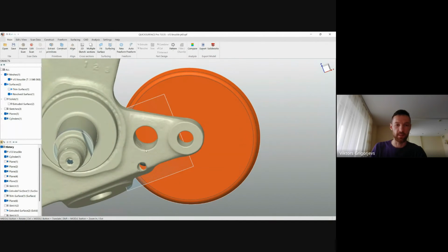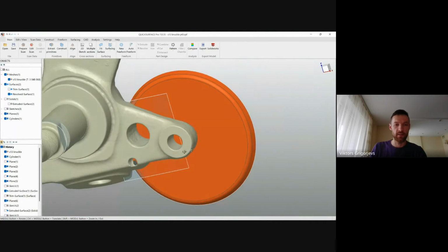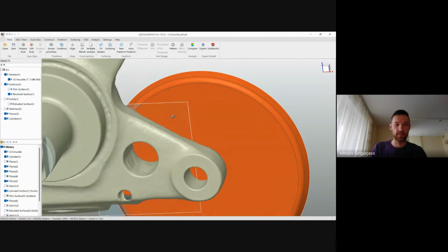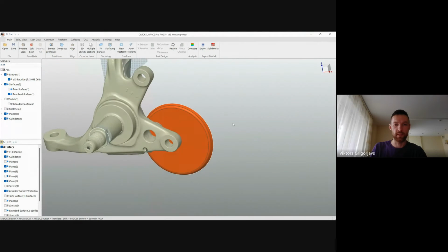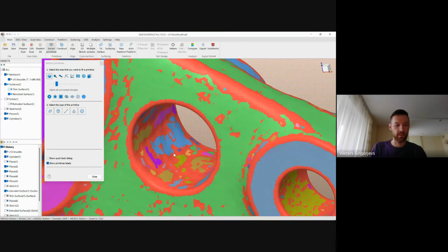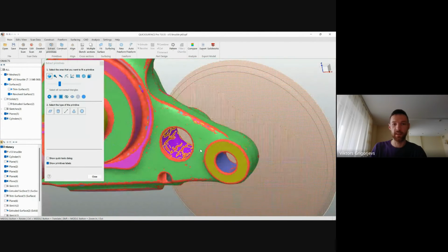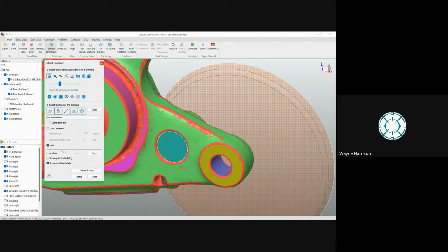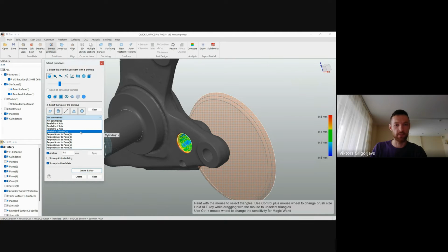Considering we still have this door here, let's create this as one single cutter. I'll just hide this plane, we don't need it anymore. So extract primitives again. The surface is a bit wobbly, not that great quality, but let's put a cylinder there and make it parallel to cylinder one.